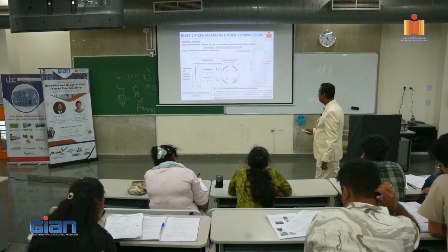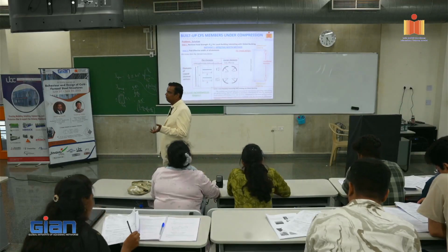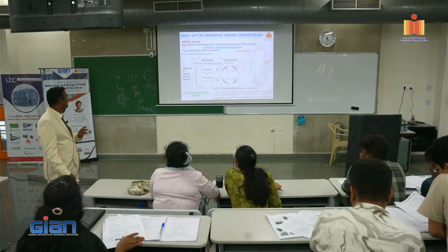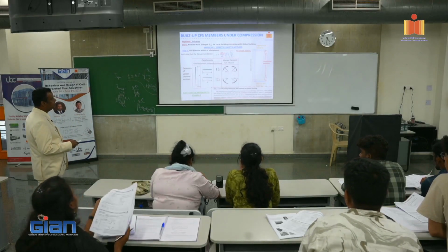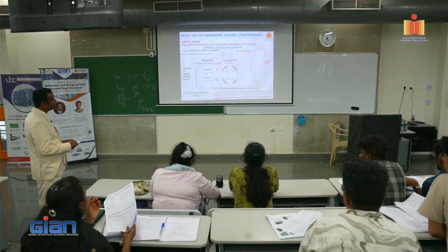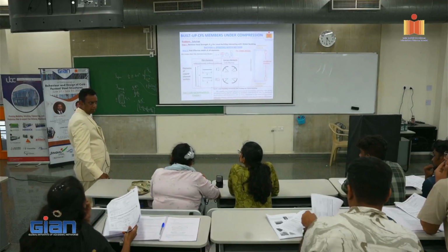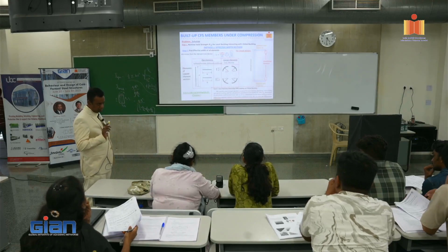Good. Now, we know that in order to calculate all these things, we have to calculate the slenderness ratio. The slenderness ratio is given by this equation: 1.052 divided by root k, into W by t, into root of Fn by E. Everybody right? Here 1.052 is a number.